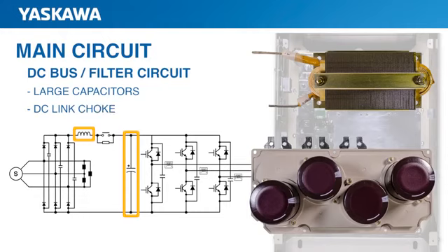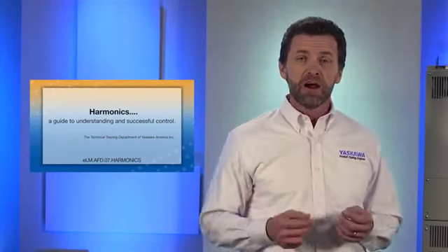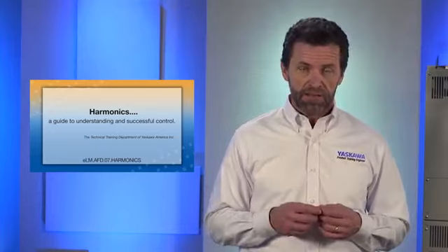In any system using a combination of a rectifier and a filter, capacitors may result in discontinuous current draw. Now, this results in harmonics being reflected back on the incoming line. YASKAWA has a video titled Harmonics that further explains this topic and ways to mitigate harmonics.